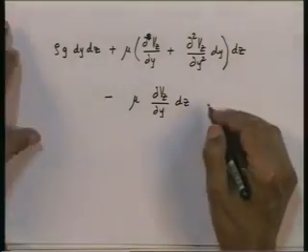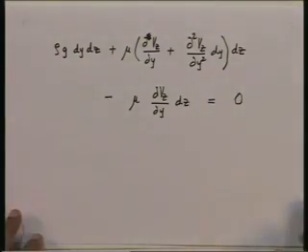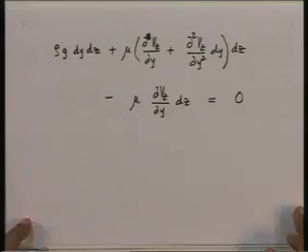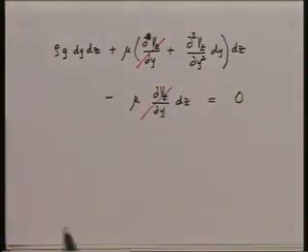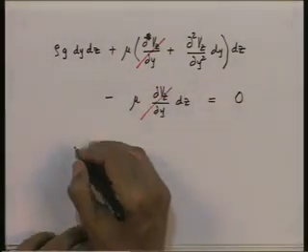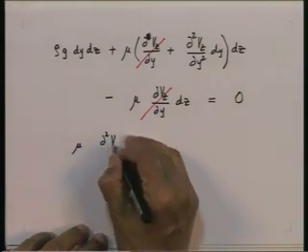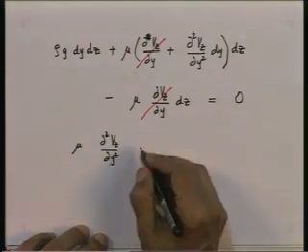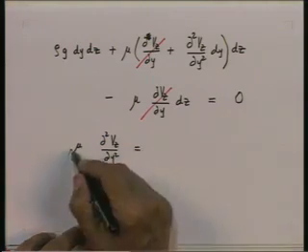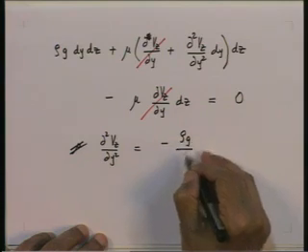control volume. And Newton's second law says, if you neglect momentum effects, the sum of all these must be equal to 0. So, if I simplify this, obviously this term will cancel with this term. I am simply going to get mu d2 vz dy squared is equal to, sorry, I will take the mu on this side, minus rho g by mu.